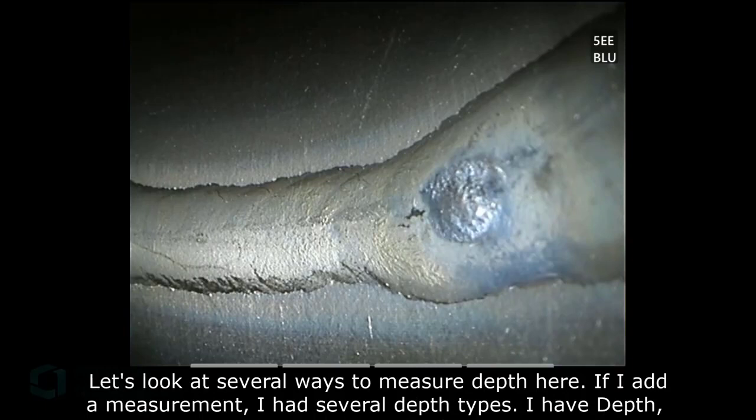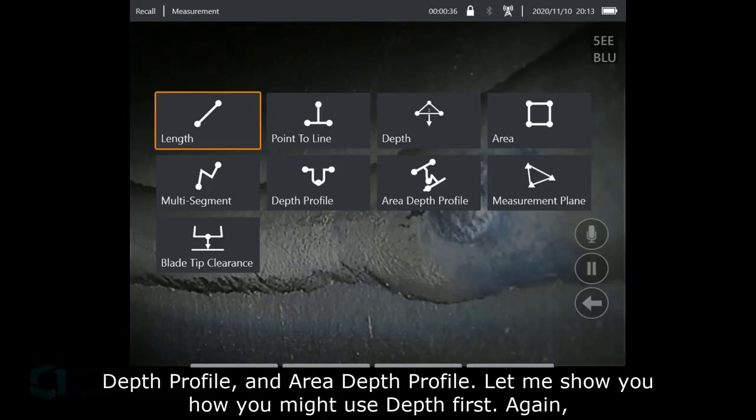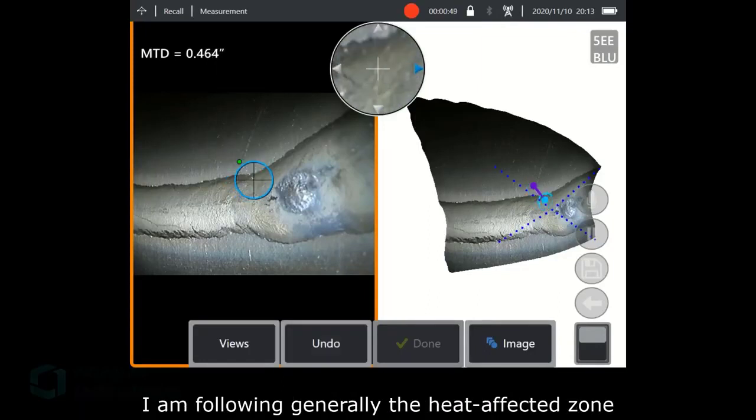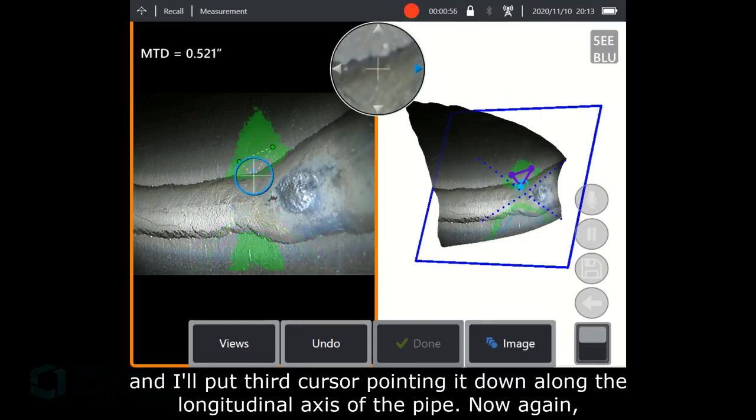If I add a measurement, I have several depth types. I have depth, depth profile, and area depth profile. Let me show you how you might use depth first. So again, I'll establish a mathematical plane with 3 cursors. I'm following generally the heat affected zone, and I will put a 3rd cursor pointing down the longitudinal axis